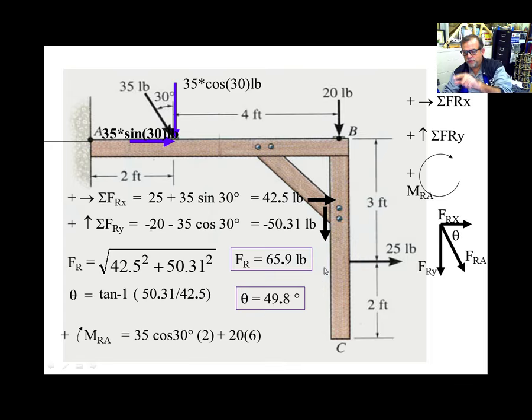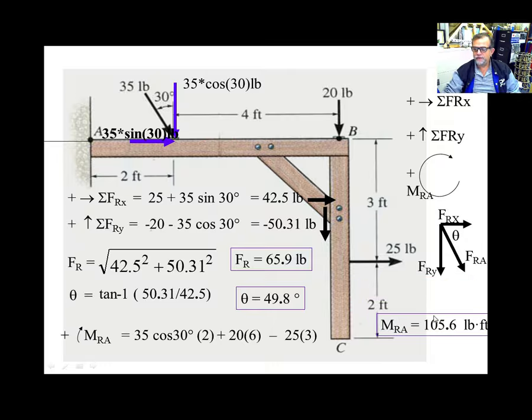Once again, put your finger over there. Let me use this thing. This is like that. Okay? Kind of like that. So if I apply the force in this end, the rotation is going to be this. So it's going to go in this way. And that way is contrary to my positive convention. That means that it's going to be 25 times 3, and the convention is going to be negative. And that would be my resultant moment at that point.